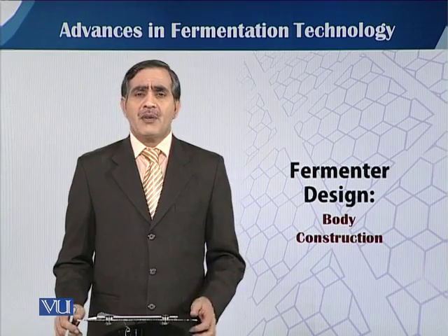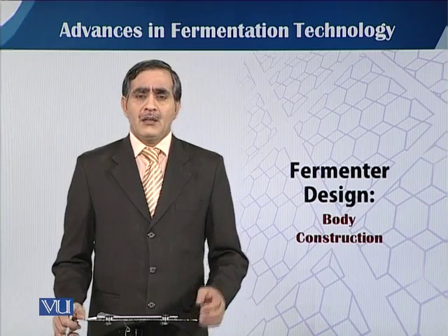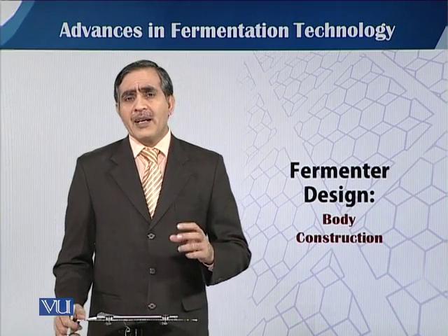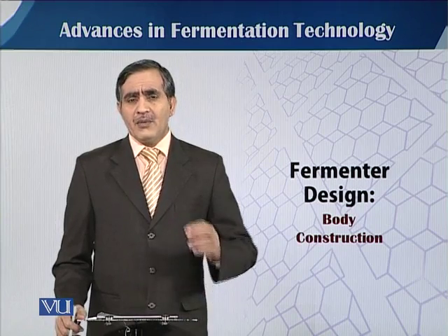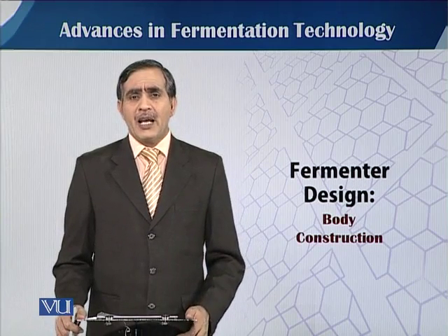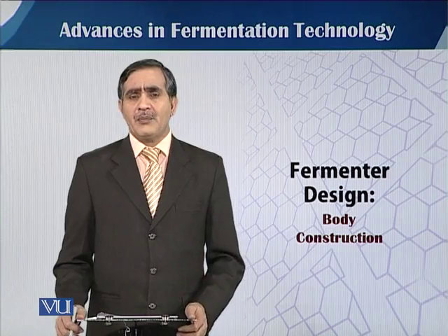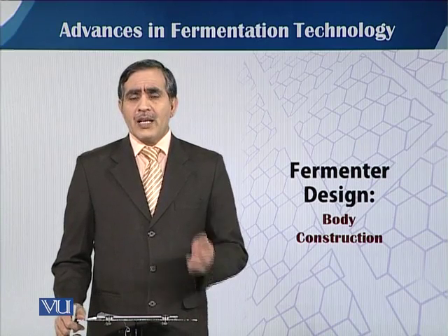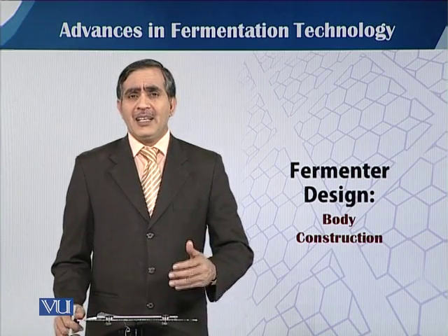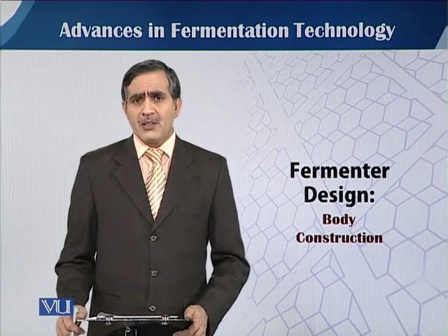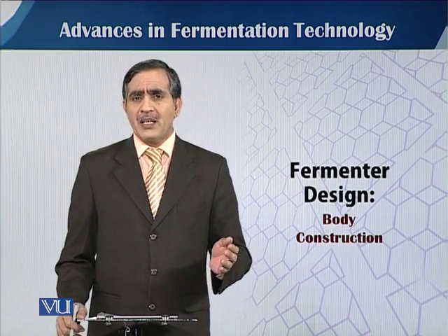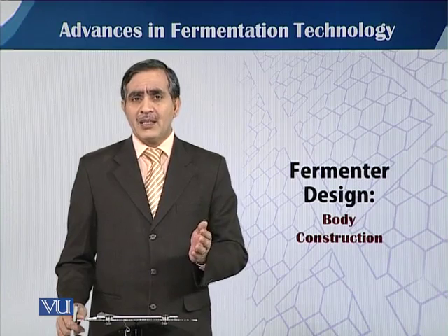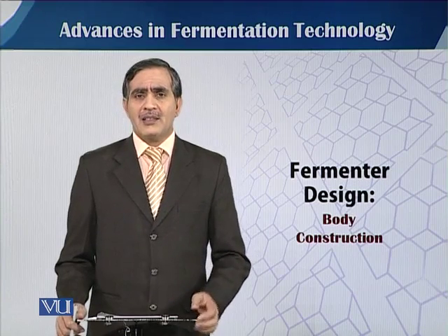While talking about the 13 basic characteristics of a fermenter, one characteristic was that when we design a fermenter, it should have an identical geometrical shape. That can facilitate the optimization process when we go from the lab scale to pilot scale and then to industrial scale.